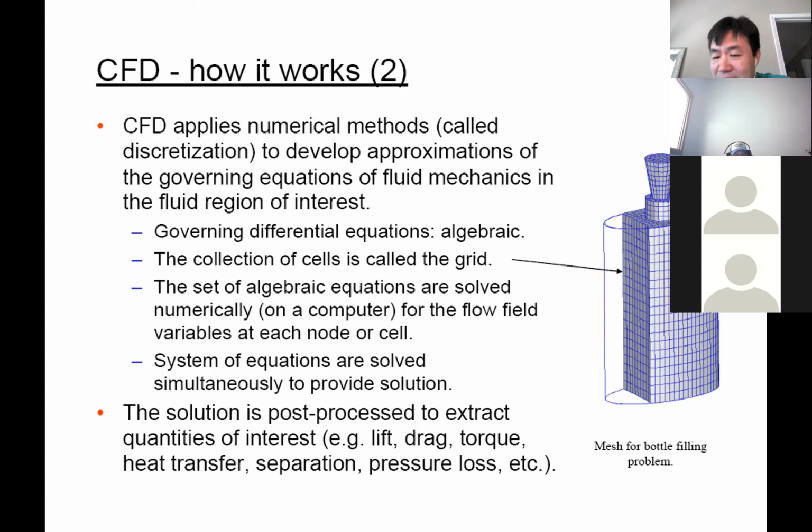Then in Fluent you still need to set it up: put in the boundary conditions, set the model, pick the correct information. Also select setups like a steady state simulation or unsteady simulation. What is the time step? Those kinds of things. Then you hit the button, and Fluent will start to run as you instructed, solving the kind of equation you wanted to solve.